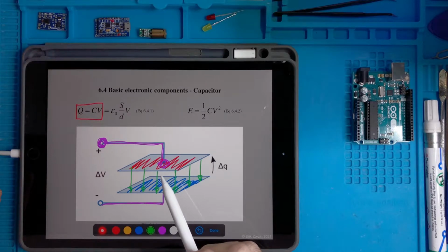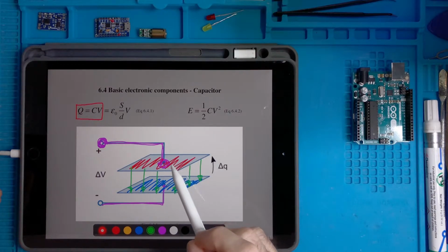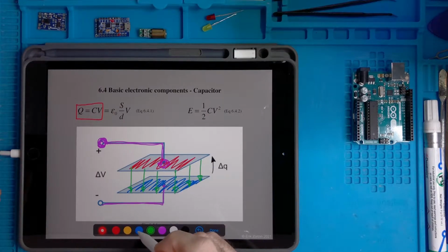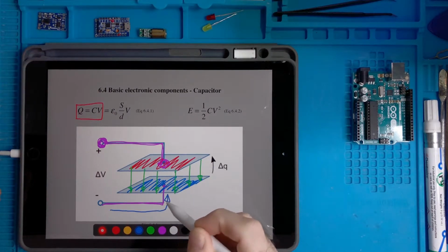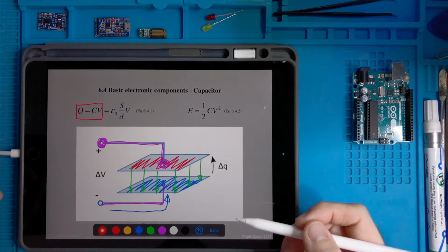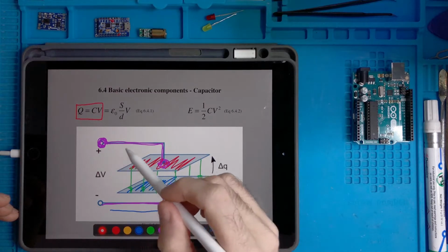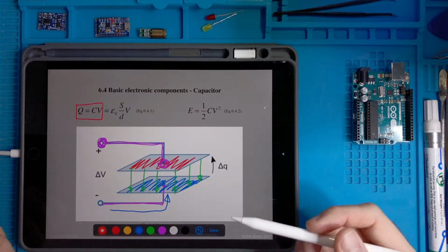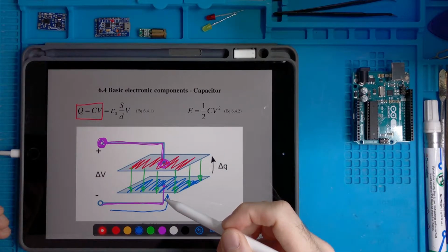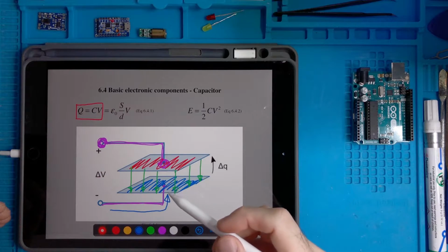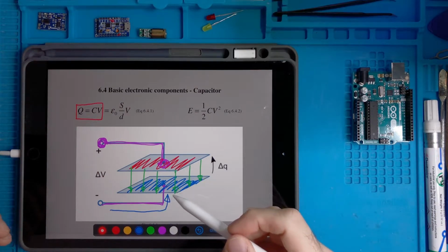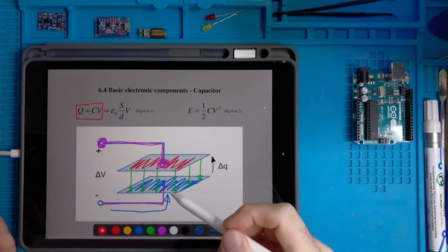So the negative charges here are attracted by the positive side here above, and this is why they want to move like this. So in the beginning the process is like this: you attach the battery, some negative charge, which are electrons, will exit from the battery, attracted by this positive side just in front of it because of this Coulomb attraction, and then at a certain point this phenomenon will stop. When it will stop? When those plates will be full of charges, so in a way that they cannot contain any more charges.